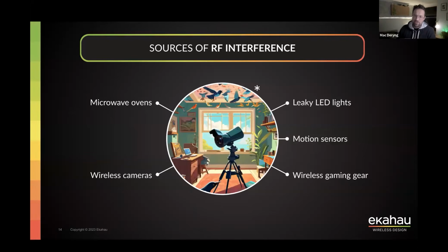Yep, and a great question from Jonas in the chat. Do APs next to each other on different channels affect power levels, for example noise? A very short answer to this question is, if you have access points on the same channels pretty much touching each other, they will increase noise due to the electromagnetic field of the radios that they create on the electronic level. If you have APs on completely different channels, the bigger the distance between the channels, the lower the noise created by the RF energy emitted by these radios.